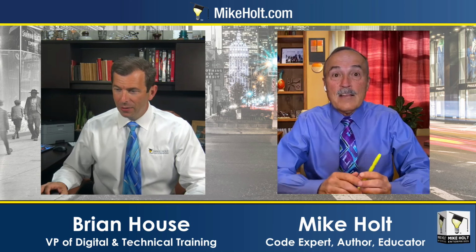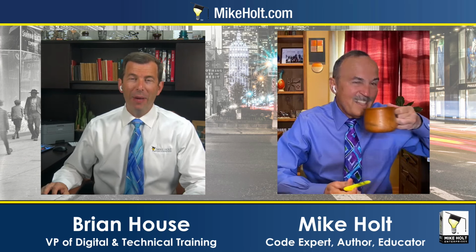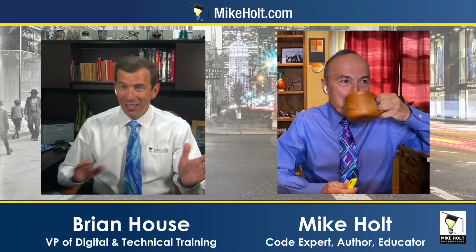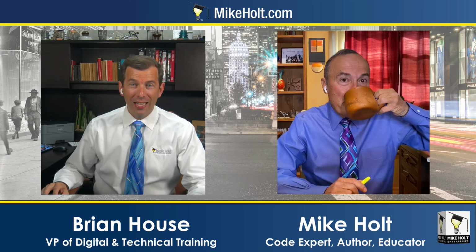Well, yeah, we got a few comments. Eric jumped in to clarify about the service point. The service conductors start at the service point. You did end up coming back around to that. So both the service drop and the service lateral are not service conductors. So yes, Eric, we hear you. He's getting real technical, and that's right. He's splitting some hairs with us.